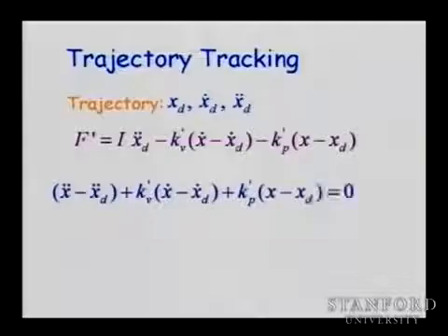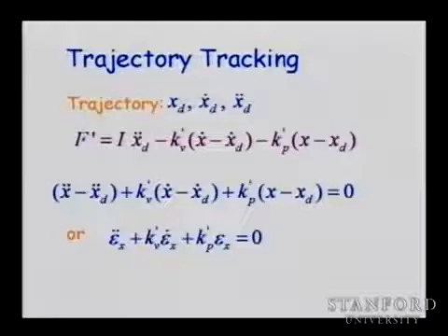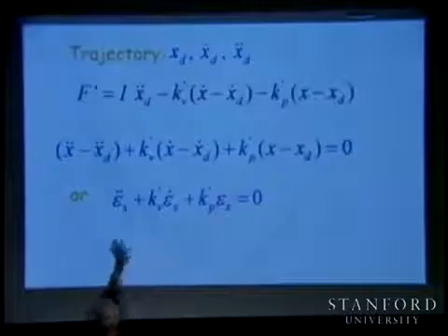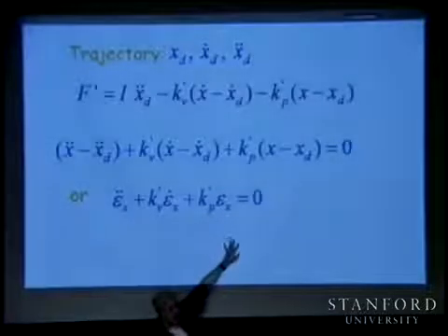You have feed-forward acceleration. You have tracking of the velocity, the desired velocity, and tracking of your position error. And the closed loop is like this, which means now you are controlling directly the error in the task space. That is, you have your camera, you are doing visual servoing, you get your x desired in real time, x dot desired, acceleration, whatever, from your sensory information, and you are able to track and control your robot to follow the trajectory specified by your feedback, and in real time you are achieving this decoupled behavior.